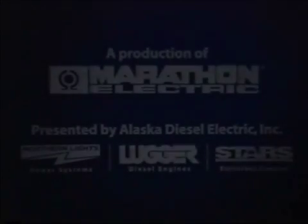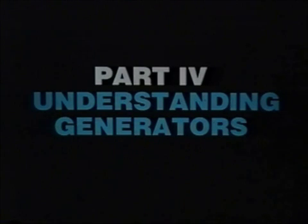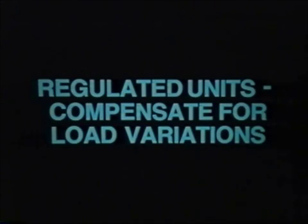Lima Energy Products, the finest name in generators, presents Part 4 of the series Understanding Generators. This presentation will focus on frequency, frequency regulation, excitation, voltage regulators, and voltage regulator accessories. Again, regulated units are designed to compensate for load or changes in load and load power factor. For this reason, they are not as susceptible to poor regulation as a result of load factors.